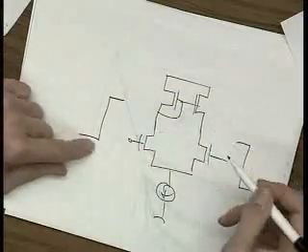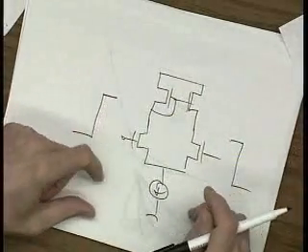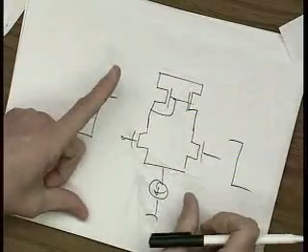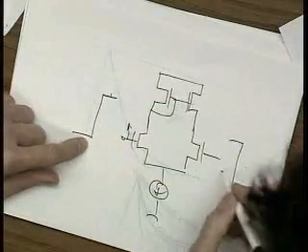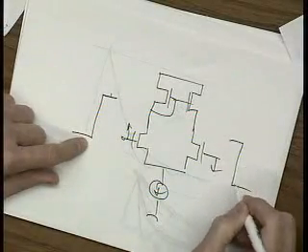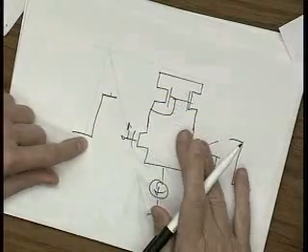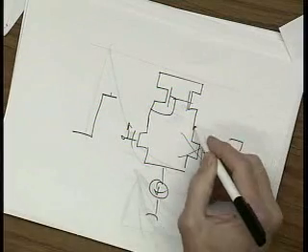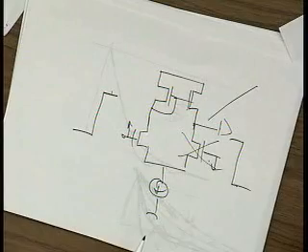Okay? You're applying at both ends, right? Yeah, differential, right? Well, if I even put it on one side, there's a common mode response. This thing moves around. So this side goes way up, and this side goes down. This turns on. This guy turns off. That's what I'm talking about. That guy turning off puts the circuit into a non-linear mode. And this output here, it's driving a capacitance, right? So it just ramps. That's what I'm talking about.